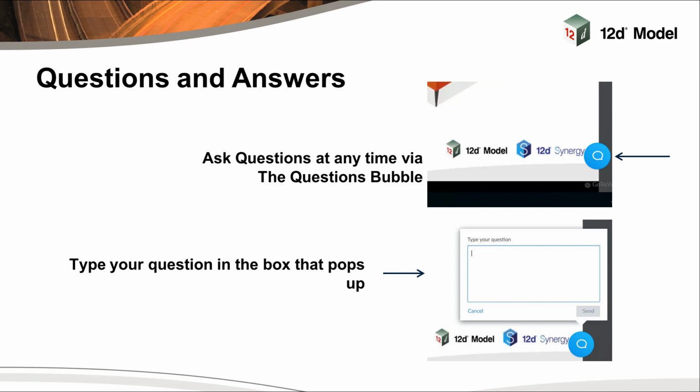Sure. Simon in New Zealand has asked, can you set the north arrow to show north automatically? That is precisely what I did by having that north symbol referenced or relative to a frame that is always showing true north, or wherever you place that symbol. So when you change the orientation of the preview frame itself, that north point automatically rotates through and always points to, I guess, the north from your underlying data in your model.